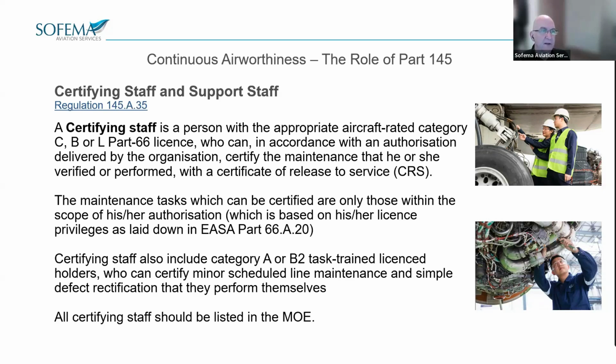Certifying staff also include Category A or B2 task-trained license holders who can certify minor scheduled line maintenance and simple defect rectification that they perform themselves. All certifying staff should be listed in the MOE.